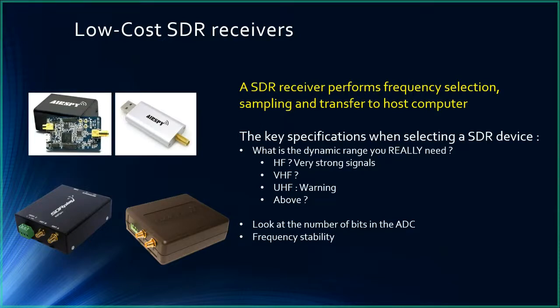the price to pay might be different. One critical thing when you use these SDR systems in HF is to filter a lot. If you can have pre-filtering, that would improve a lot because that would reduce the unwanted strong signals that could enter your ADC and put it in a very bad position where it has to decide if it keeps only the very strong broadcast station or the one you are looking for.